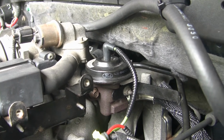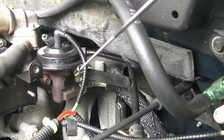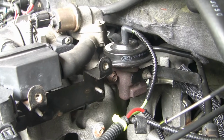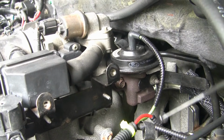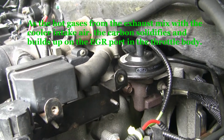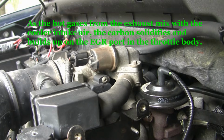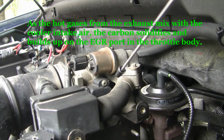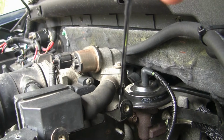In any regards, if it's not the DPFE sensor, the other big problem is it's probably clogged somewhere. And watching the other professional mechanics on YouTube, they say when it's clogged, just about everybody I've seen, the problem is in this throttle control body. And what they actually have to do is they take all these hoses off, pop this throttle control body off of there, and clean the carbon out from the port, the EGR port.